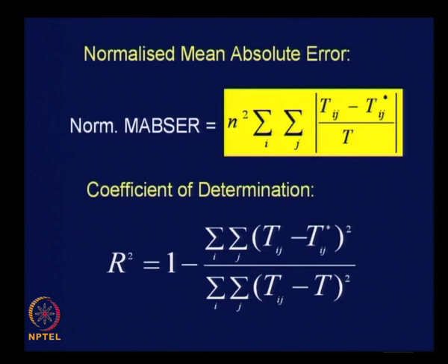We can use any one of them or use all three and then take an overview of the comparison and choose the alpha value which gives you the least error. Is that clear? So, with this basis, let us take a small numerical example and try to understand the procedure of calibration of the doubly constrained gravity model.